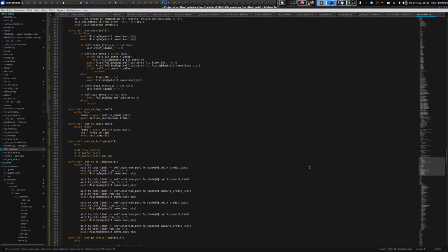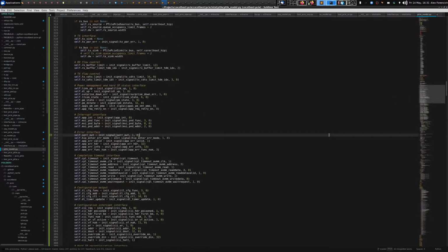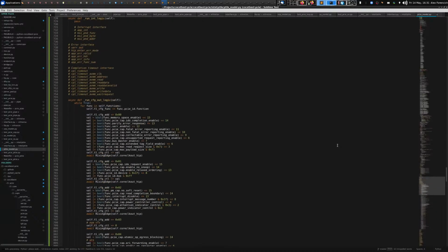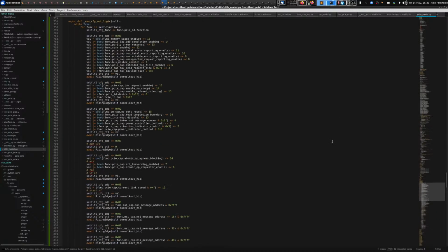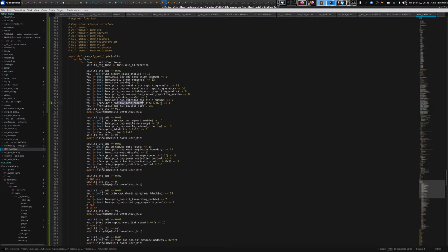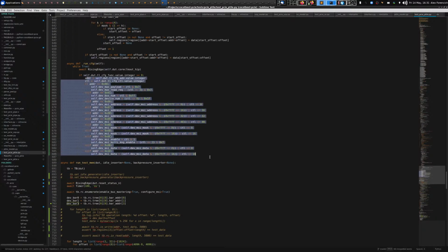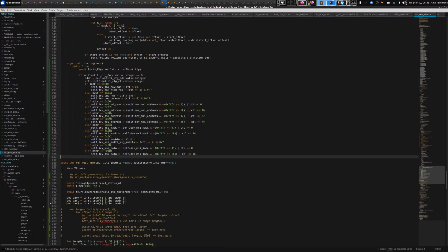But on the Xilinx IP core, they tend to provide a lot more stuff just directly on signals. That does make it a little more complicated to interface with, because you have to write a bit of additional logic to peel off some of the fields that you need, like the max read request and the max payload size. But it's only a handful of lines of Verilog. To be honest, it probably makes a bigger difference in terms of building the verification components, because you need a bit of additional logic here. This is the other end of it that extracts the information from that interface for the MSI address, the payload size, the read request size and whatnot.